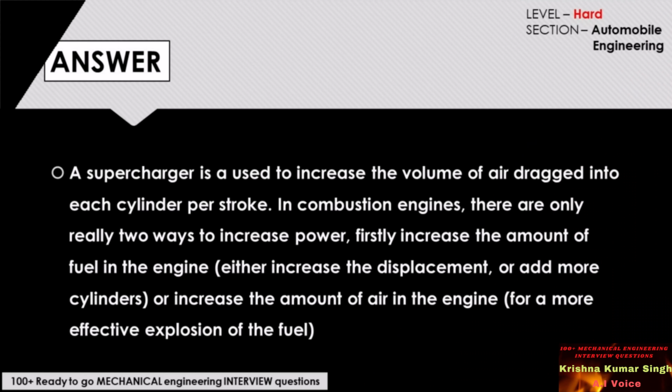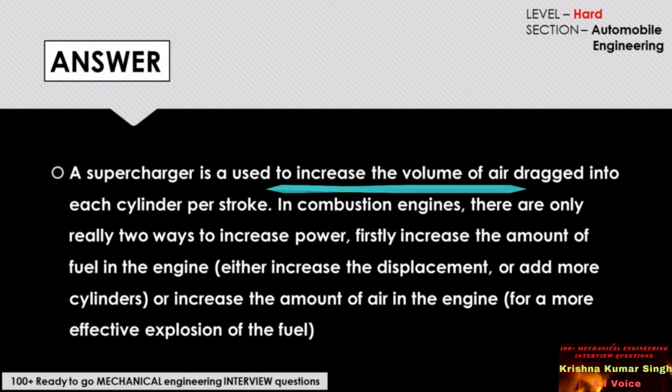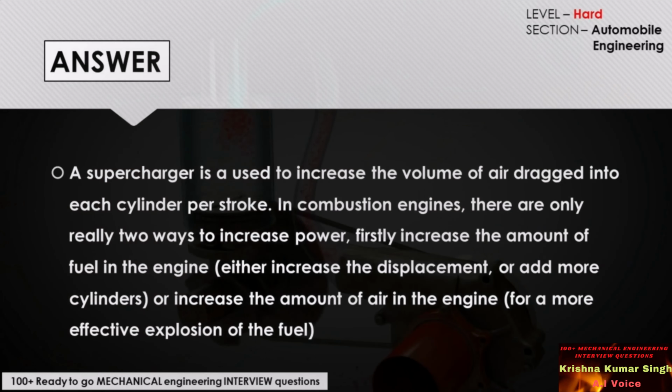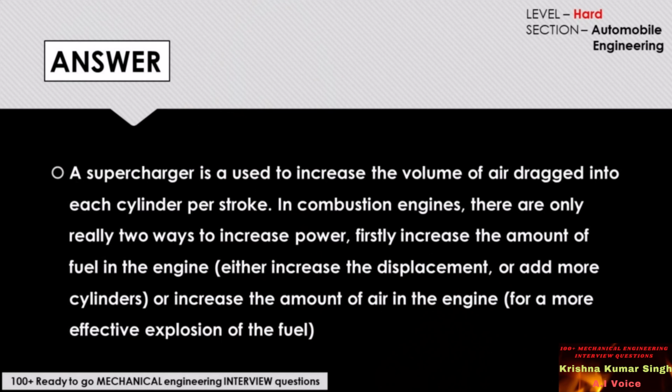The perfect answer to this question would be, a supercharger is used to increase the volume of air dragged into each cylinder per stroke. In combustion engines, there are only two ways to increase power. Firstly, increase the amount of fuel in the engine. Or secondly, increase the amount of air in the engine.